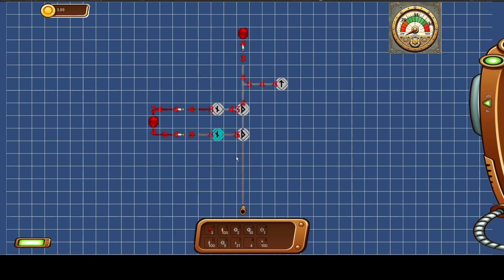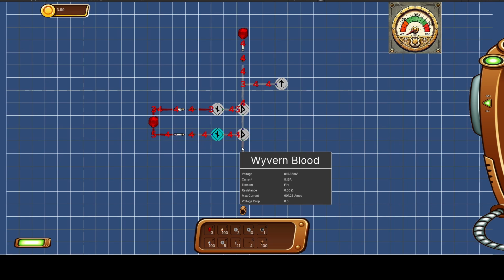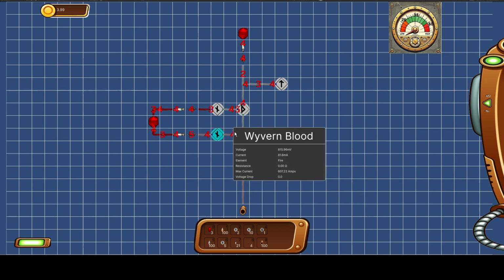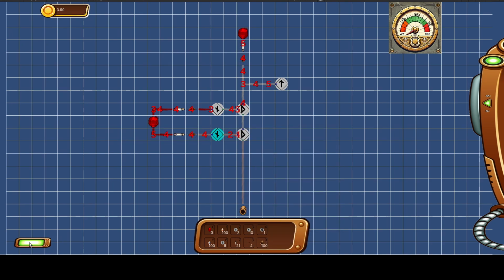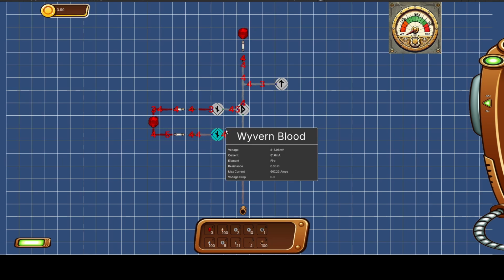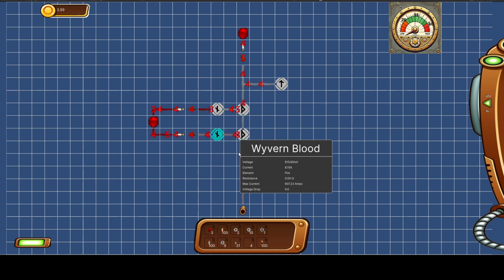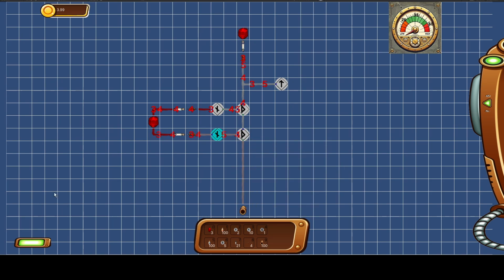If I were to bring this up, you'd see there's about 815 millivolts on this, which is the same as you have over here, because voltage does travel along here, and so would current. The current does go, but the magical charges don't. They go to ground, and there is a 10 ohm resistor across the BE connection there. So that does contribute a bit here.